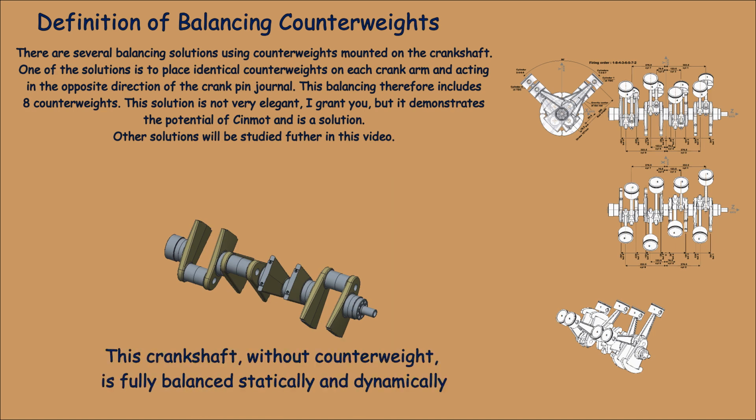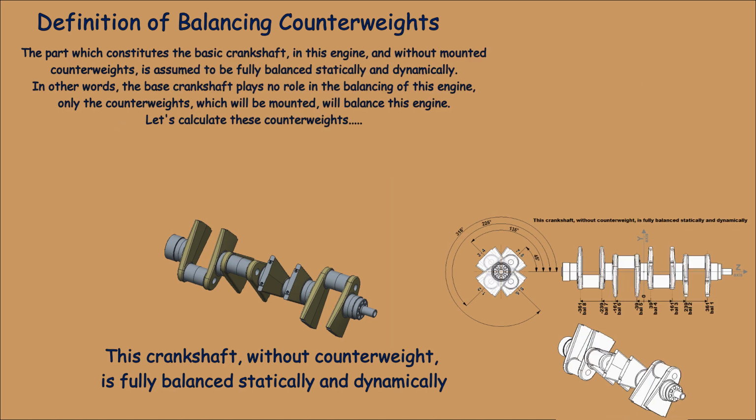This crankshaft, without counterweight, is fully balanced statically and dynamically. The part which constitutes the basic crankshaft, in this engine, and without mounted counterweights, is assumed to be fully balanced statically and dynamically. In other words, the base crankshaft plays no role in the balancing of this engine, only the counterweights, which will be mounted, will balance this engine. Let's calculate these counterweights.